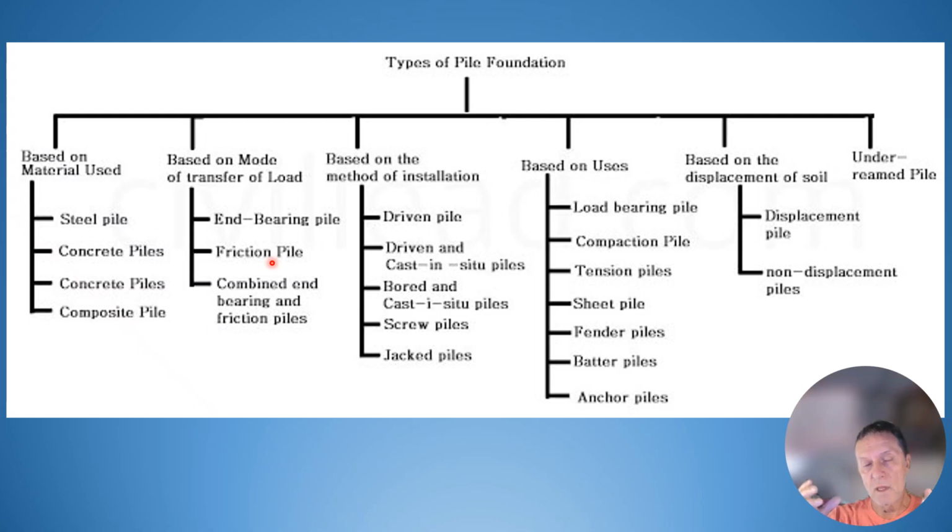So that might be an addition to strength based on friction on the sides of the pile as well as the strength of the material at the bottom of the pile. You can install piles by driving them or drilling a hole and putting concrete into the hole. You might screw in a pile, or you might jack in a pile with a jacking mechanism.